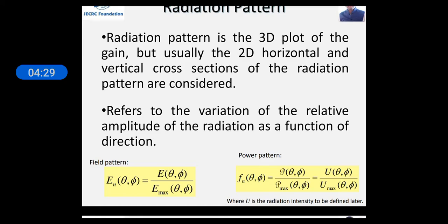So we know what signal we are transmitting, and observe the received signal at the test antenna. At that particular angle, we get a transmitted signal power and received signal power. So we calculate the gain for the test antenna, that in what proportion it is receiving the energy at that particular angle. Now start rotating the test antenna with any step size, you can take 5 degree, 10 degree, 15 degree.